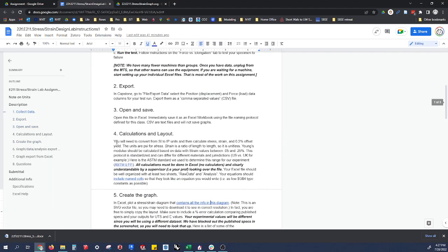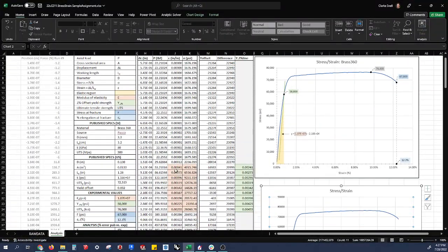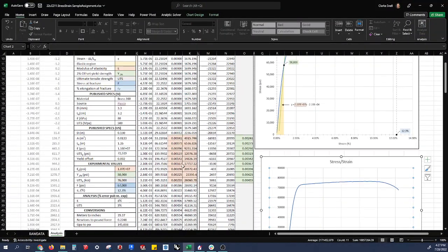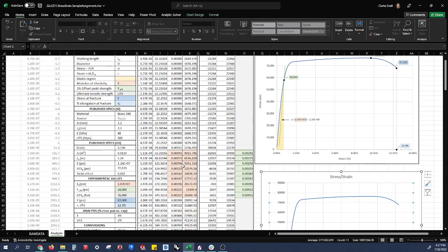That's described here in this paragraph, and there's a question about why you think that might be true, so think about it. But the point is that if we identify where 0.05 and 0.25% strain is, and take the slope of the stress and strain for those data points, we can calculate the Young's modulus.